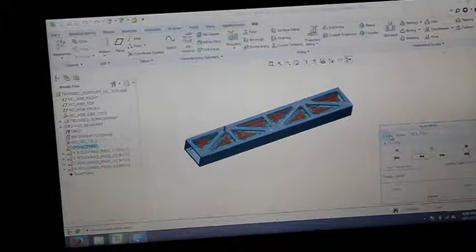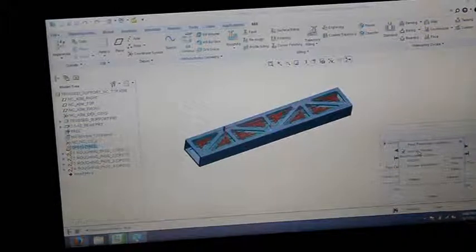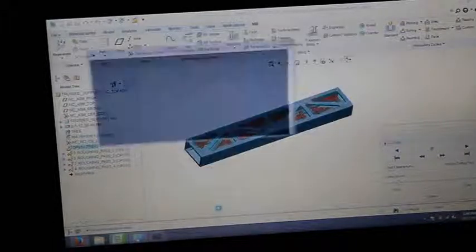Now, if we know that this is something that we want to use on the CNC machine, we can just stop the operation, and we can actually go to File, Save as MCD, and you go Save CL File also, and you can click Output. So in this case, we're just going to call it op01. We can call it a number of things, but we'll just leave it as that.